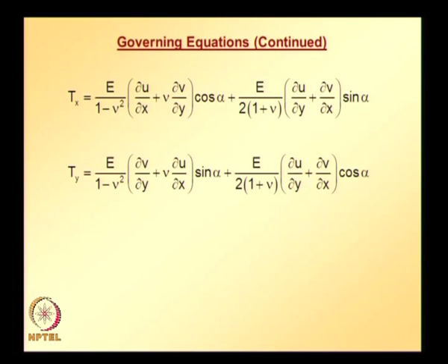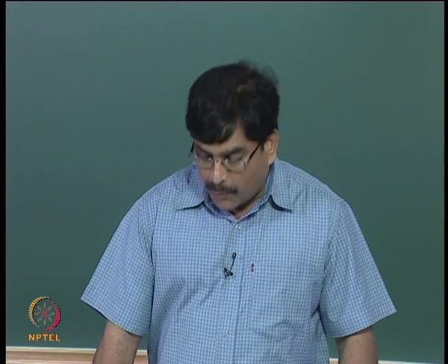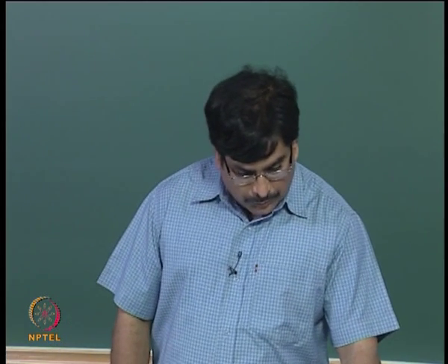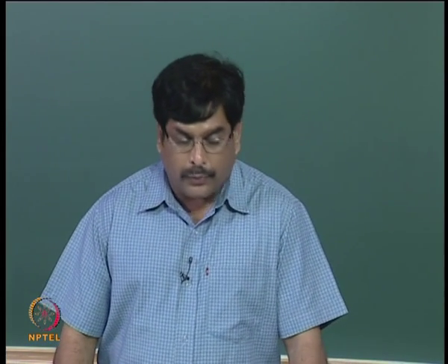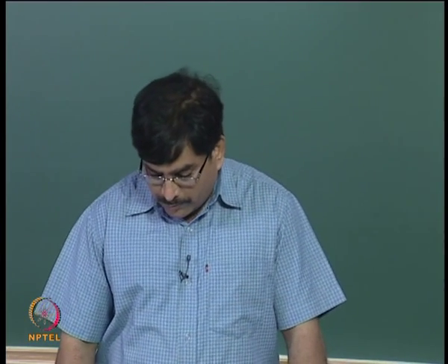So, tractions are indeed natural boundary conditions because they involve first derivatives of displacements, whereas displacements are zeroth order, which are essential boundary conditions. So, equations comprising first order derivatives are going to be natural boundary conditions. Thus, the applied surface force boundary conditions involve first derivatives of displacements, hence they are natural boundary conditions for a second order boundary value problem.